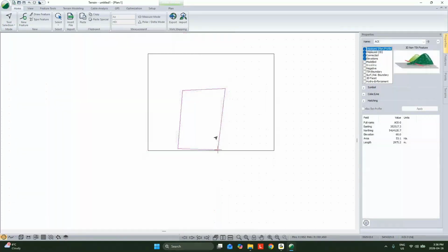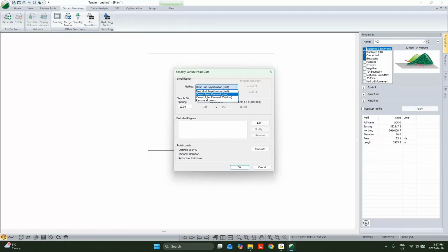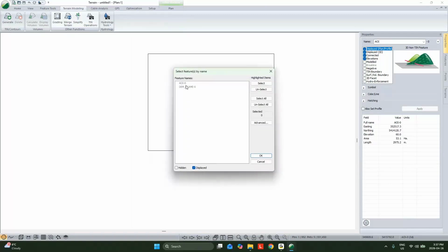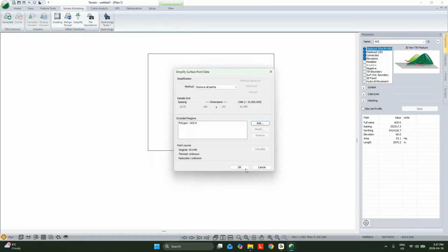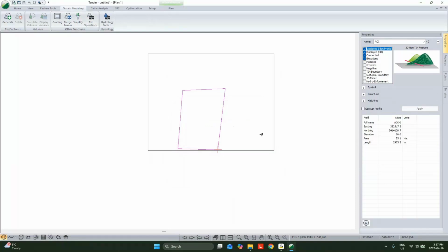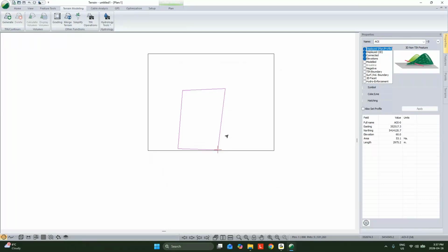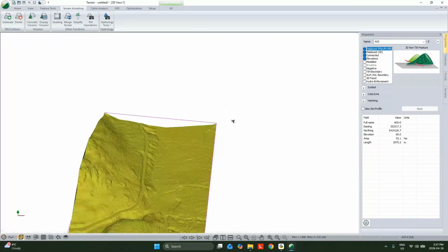You can mix and match. You can try thinning on import and then realize, oh, I'm not as small of a file as I'd like, and maybe we do even more. So we could thin it afterwards too. So I'm going to just remove all the points outside of that polygon. Now those thinning tools that we've introduced work the same whether we're using them for DEM data, LiDAR data, etc. Whatever's modeled, they behave very similarly.